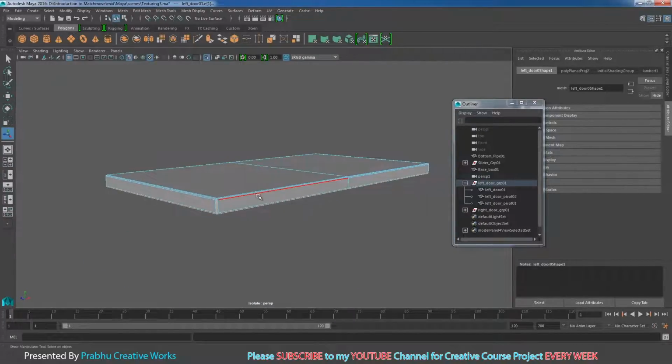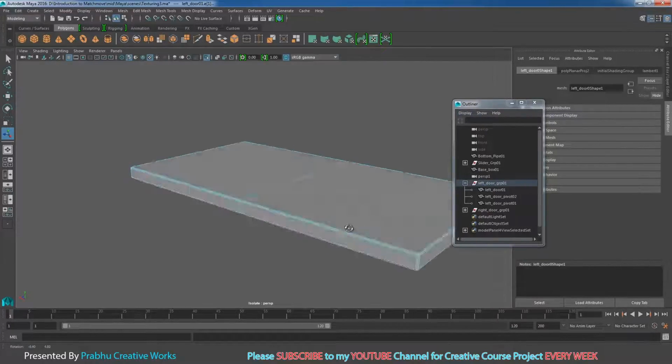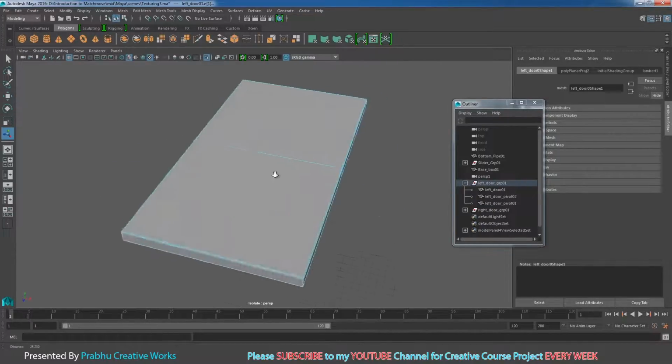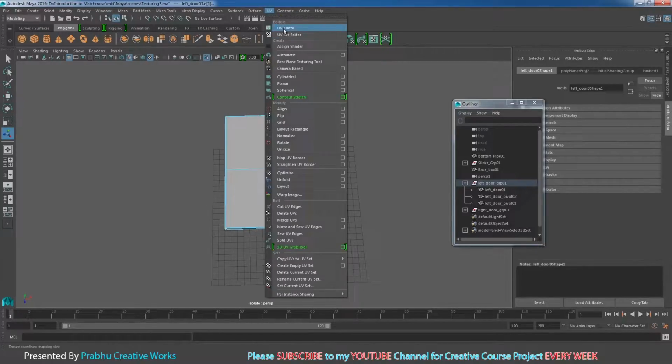So if you have doubt, rewind this video. So it's very simple. You want to select this 3 corner edge over here and then also you want to select 3 corner edge over here and then you want to select only 1 corner edge on this side. That's it. Now go to UV and choose UV editor.